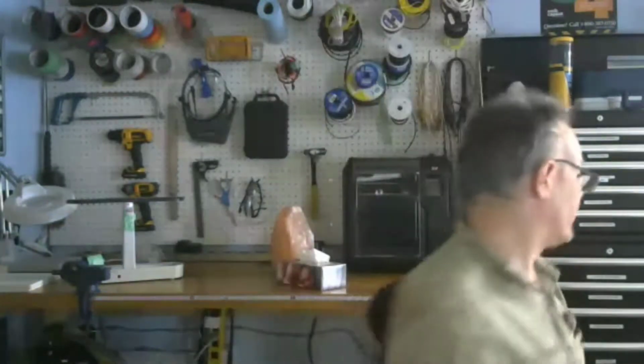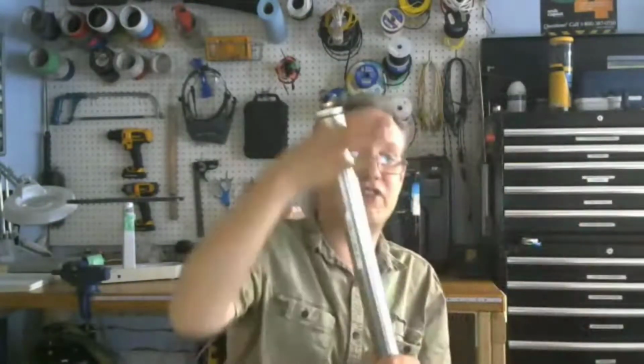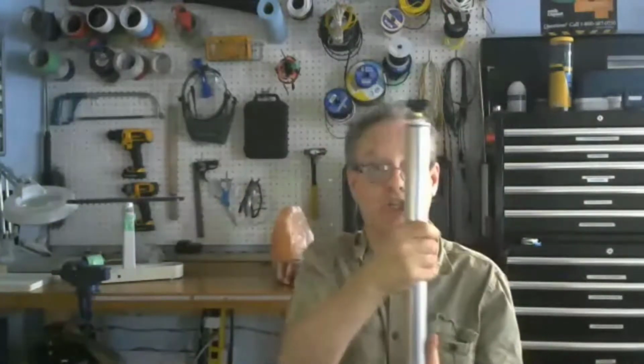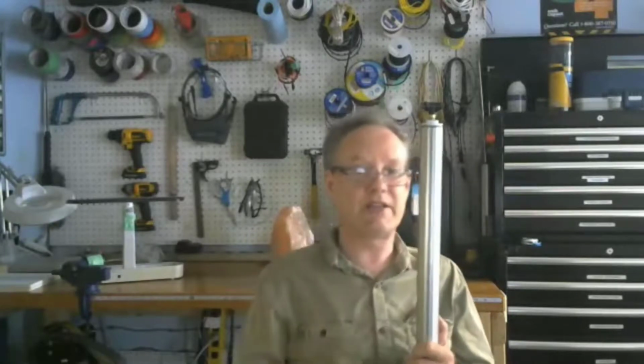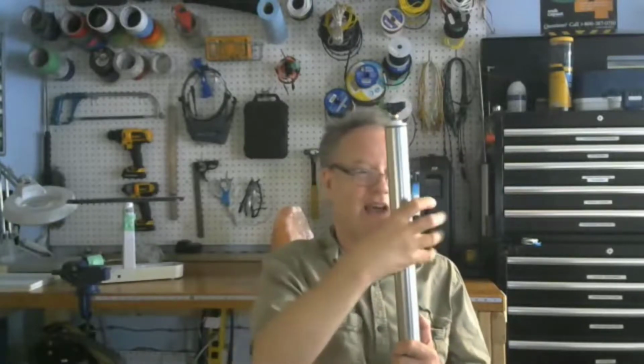Therefore, more force without higher flow rate will make up for the larger volume. Do you know what? Yes or no? Essentially, it all depends. But you have made the assumption that a larger cylinder can handle higher pressures. Actually, a smaller cylinder can handle larger pressures because force and pressure are linked to surface area. If I were to find the surface area of this whole thing, it's much larger than the surface area of that tiny cylinder. So if I put 100 psi in here or 100 psi in the other one, this has a lot more force trying to break it.